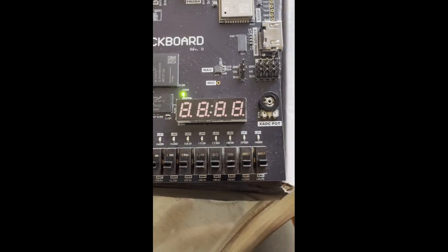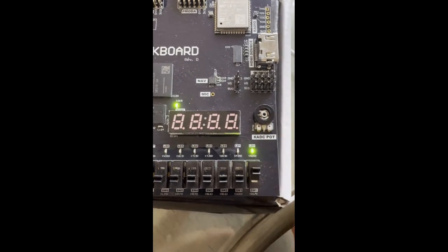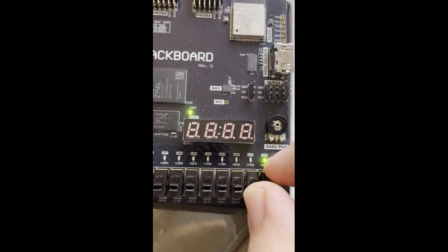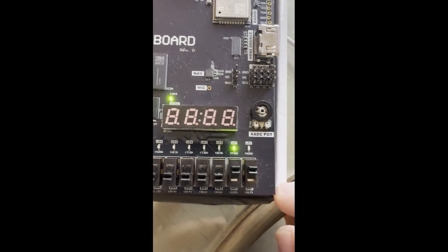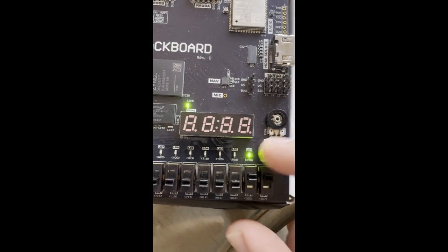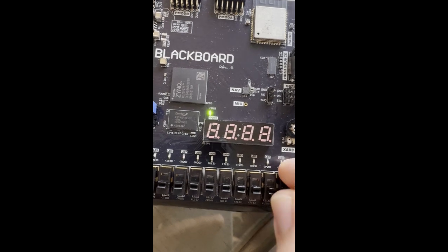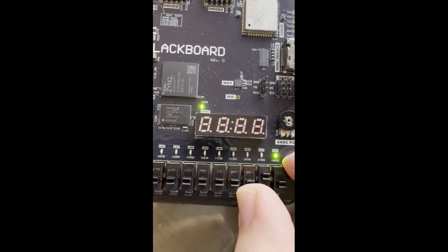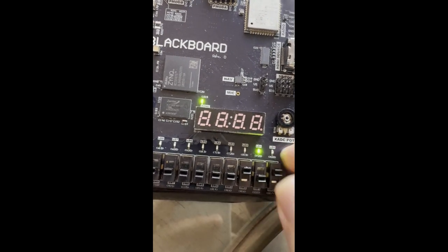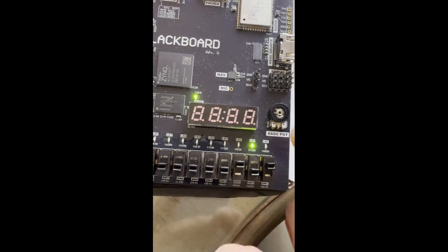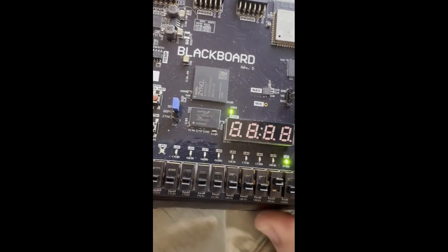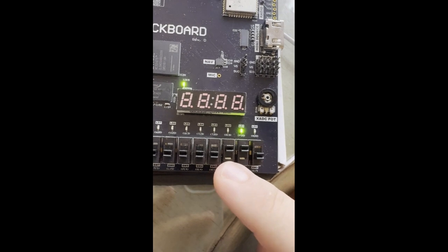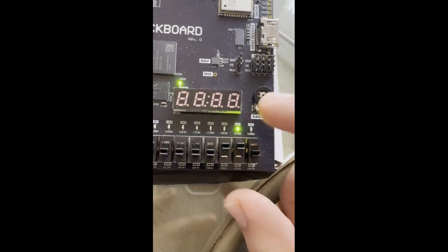And so when we enable input A, we have 1 on our sum, 0 carry. Input A and B, we have 0 on our sum, 1 on our carry. And input B, just 1 on our sum, 0 on our carry. A and C, we have 0 on our sum, 1 on our carry. C and B, we have 0 on our sum, 1 on our carry.